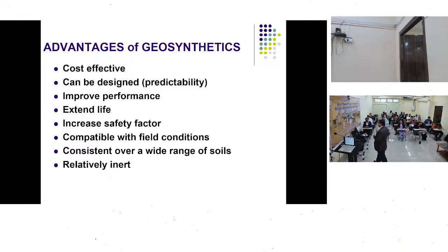Now, in that case, suppose you are not introducing a layer of geotextile as a separation layer, basically I am going for the repair of my road every year. Once I introduce a layer of geotextile in between, it may be costly. The initial cost may be high, but if you look at it over a period of maybe 3, 4 or 5 years, it becomes cost effective.